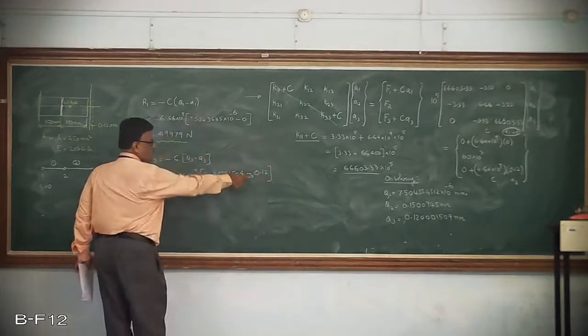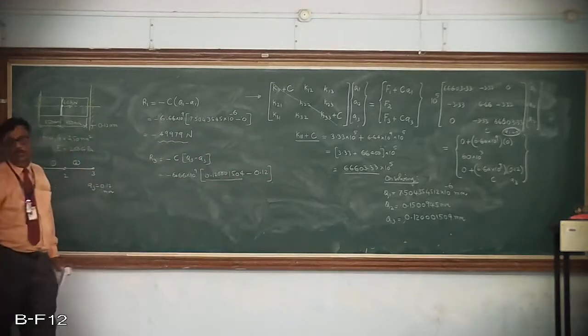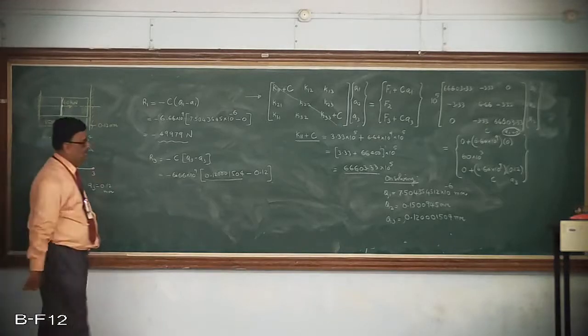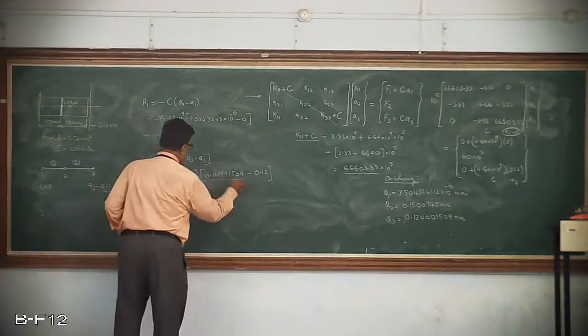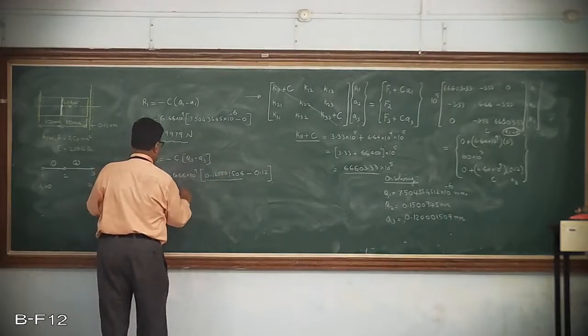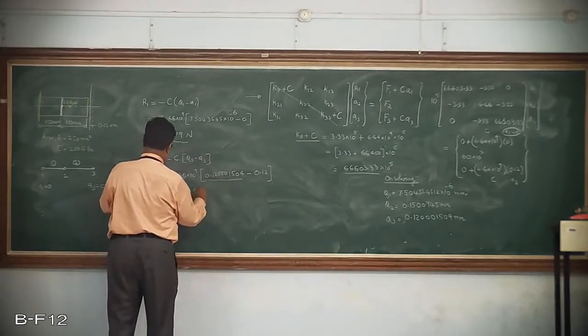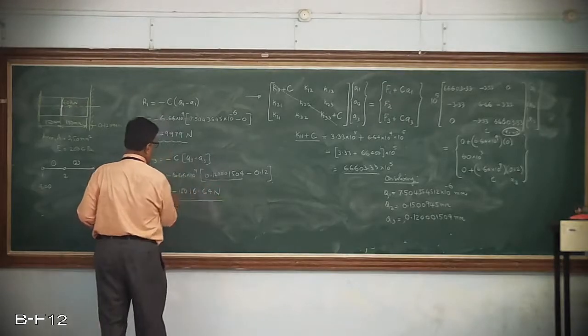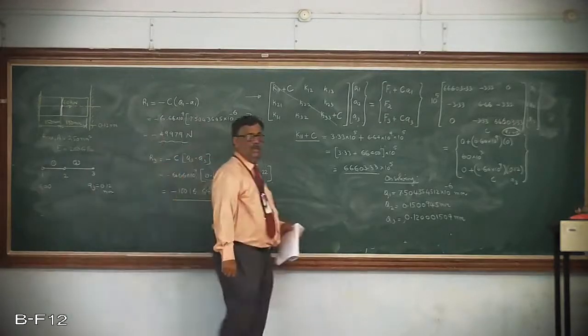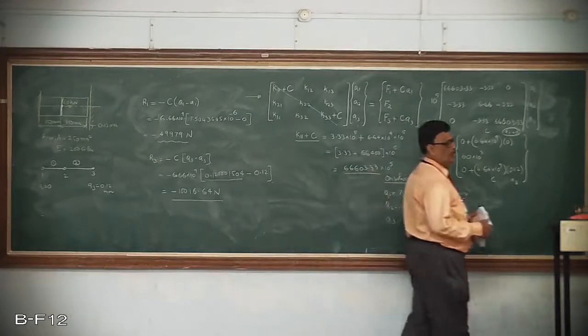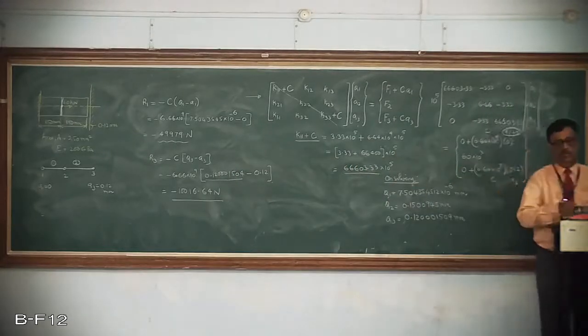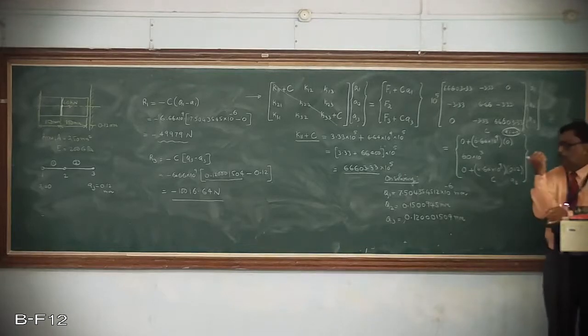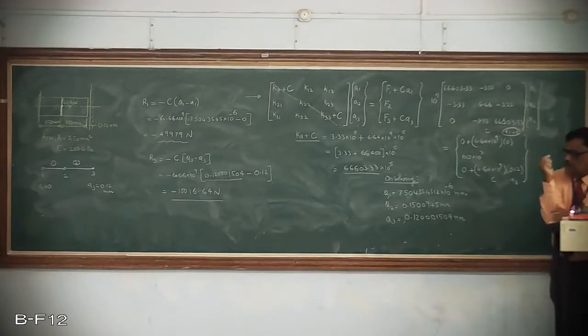This needs to be considered because A3 is 0.12, whereas the nodal displacement Q3 that you calculate is slightly more than that. So when you really take these two, you will get 116.64 Newton. So this and this, when you add it together, once again they should come equal to the total load which is going to be applied there. So I think definitely you can compare the displacements and the reactions obtained from the elimination approach as well as from the penalty approach. We find very close resemblance.